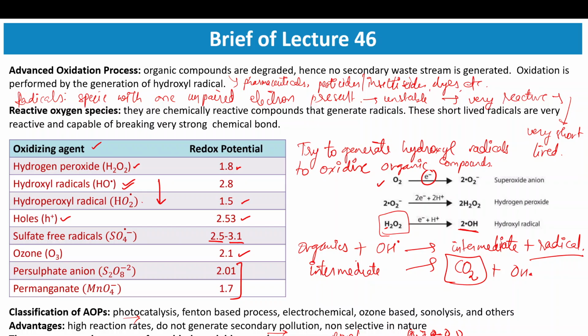So out of the entire COD, the biodegradable component is much higher, right? So you can term this as biodegradable, and you can achieve all major degradation through biological process only. But if the BOD to COD ratio is very low, let's say you have BOD to COD 0.3 or 0.4, then you need to use some process, including advanced oxidation process, for the oxidation of non-biodegradable organics.